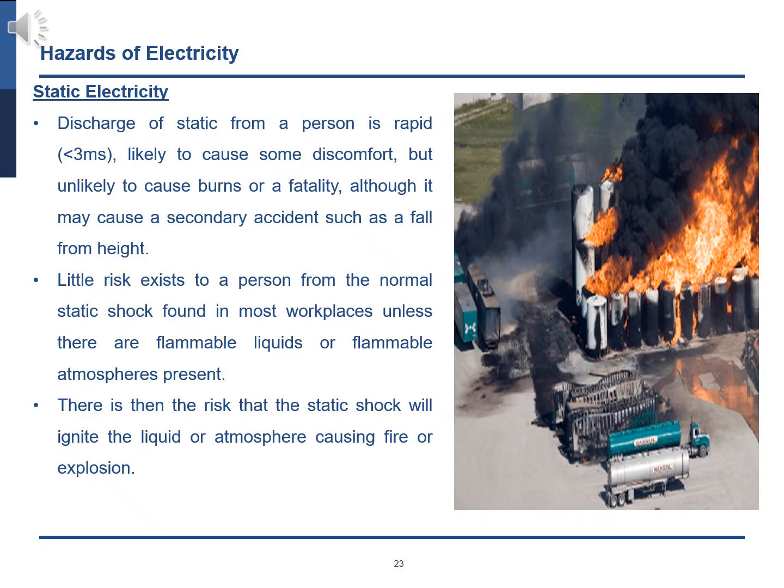Little risk exists to a person from the normal static shock found in most workplaces unless there are flammable liquids or flammable atmospheres present. There is then the risk that the static shock will ignite the liquid or atmosphere, causing fire or explosion.